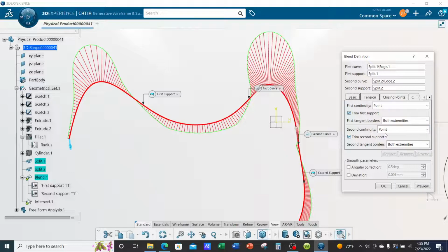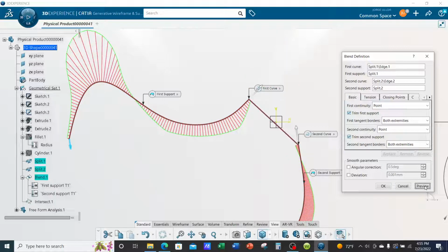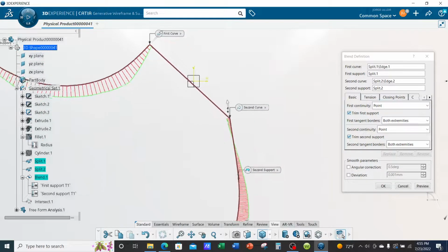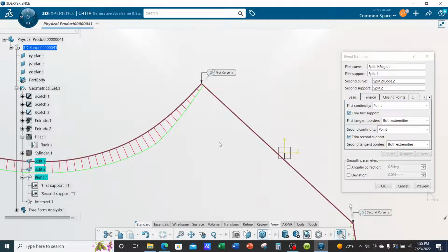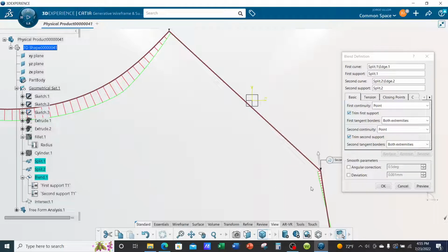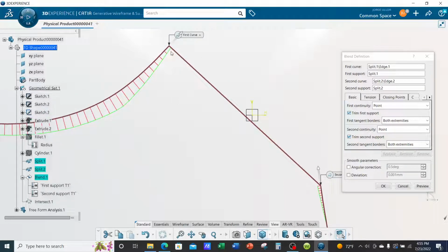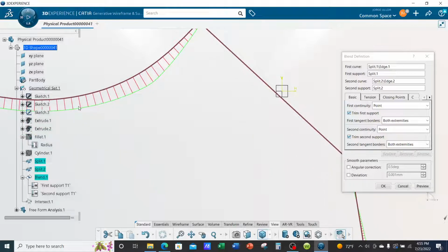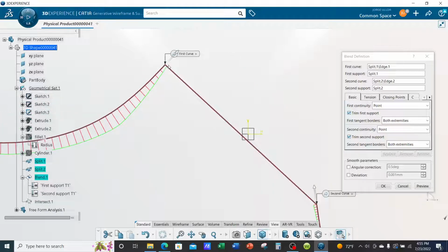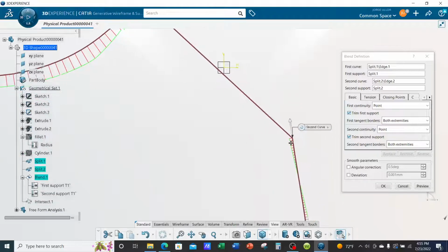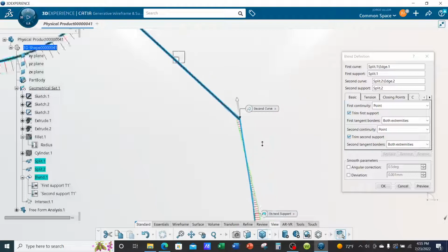Okay, so we're dropping from G2 down to G0. And hit preview. Notice what happens to our Porcupine. Okay, so our Porcupine doesn't like it, right? All of a sudden, there's a drop. It's not a smooth, clean transition on the green line that we see here, right? All of a sudden, it just stops. Then it continues on over here on this side, right?